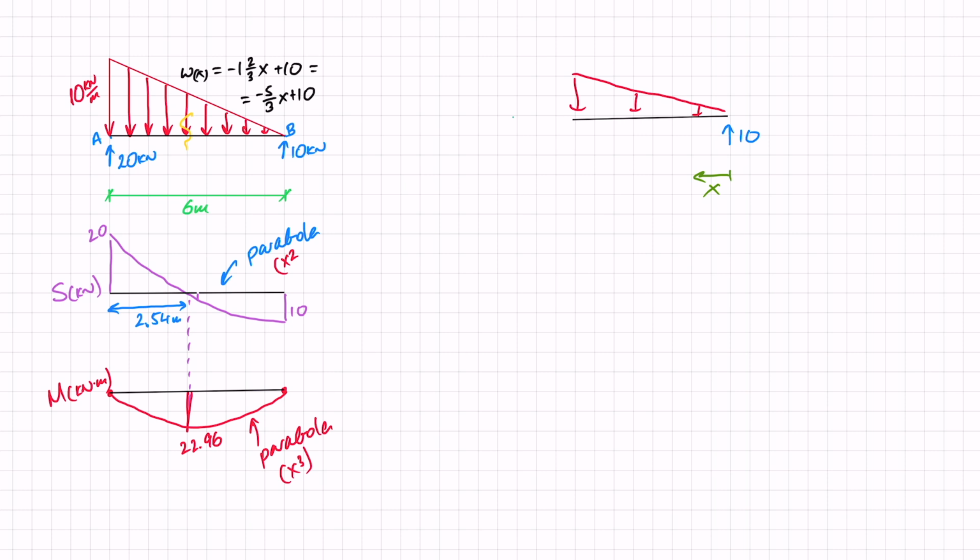And the only thing I need to be quite consistent is that these are internal forces. So they need to be equal in value, but opposing in direction to the internal forces from the other side, right? Because these are all internal. So the minute I close everything up, they have to disappear. So before I look at the forces, the only thing I'm really missing is I need to find the height here, which is also the function of this load at any given x.